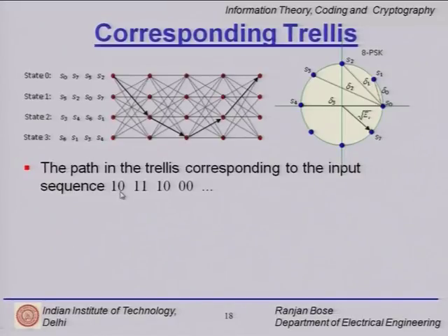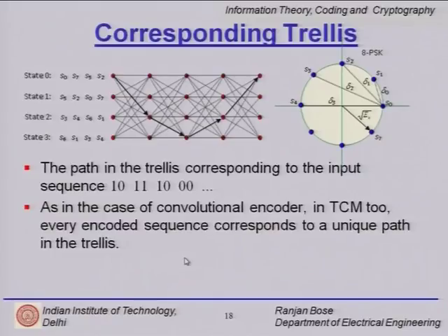Since encoder and decoder are friends, we know that 2 bits are encoded at one time, and the encoder then takes 1 0, means takes the third path, then 1 1 take this path. This basically gives the direction to take, which sequence of bits will define that a certain path in the trellis must be traversed. And what we do is simply read out what is written on top of each of the branches.